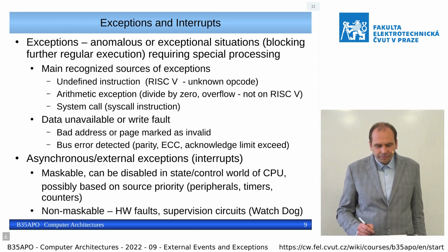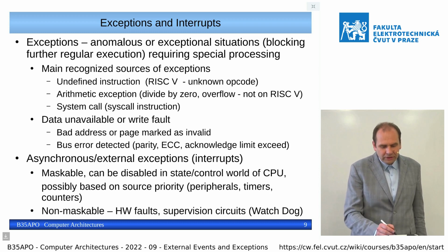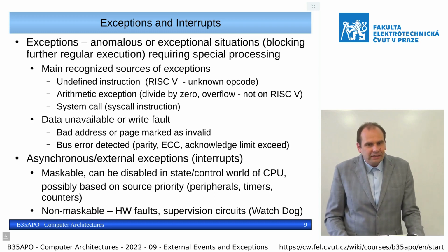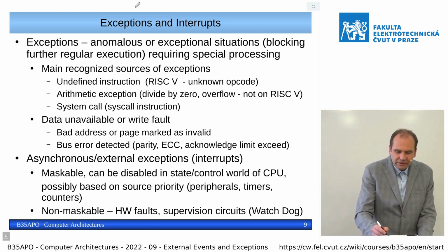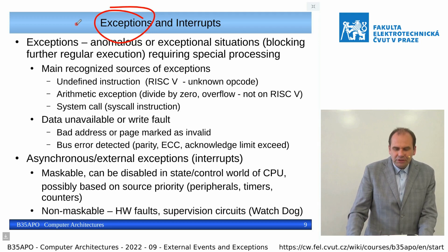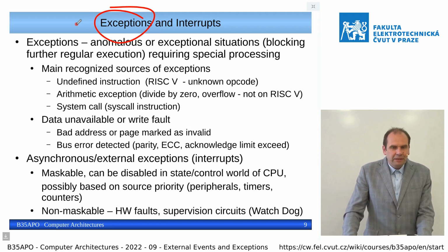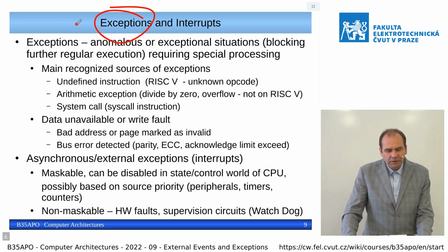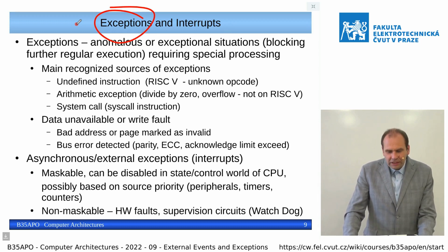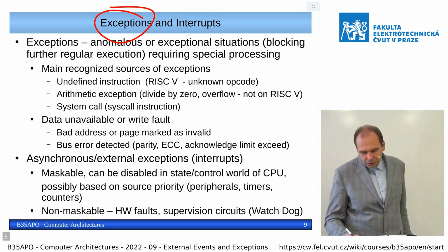And there is a little problem because the mechanism to process the exceptions and external events is quite often combined in the processor, and some producers use the term exceptions for the external events and even for the synchronous exceptions caused by the instruction execution.